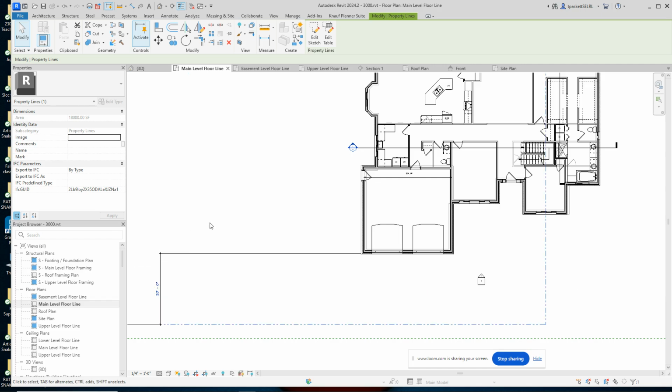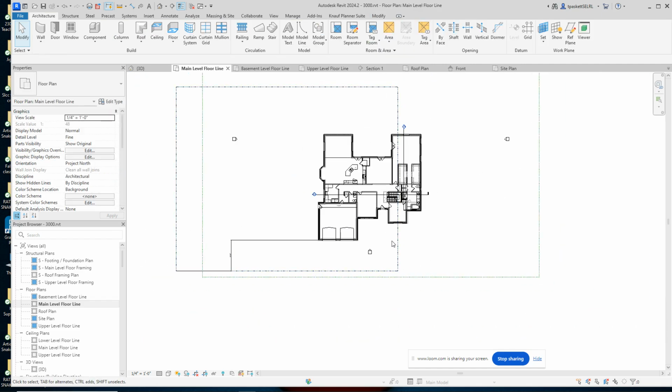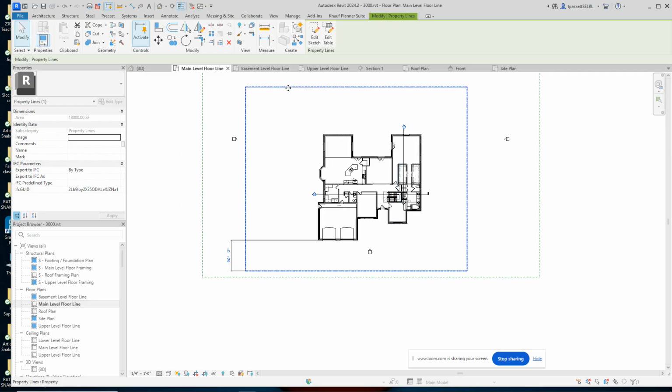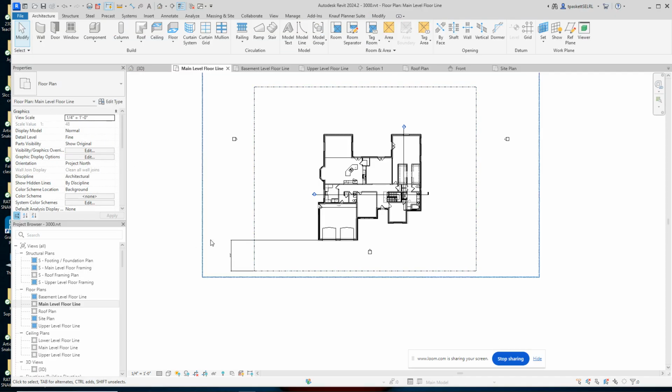Now what that's going to do, that means we've got a pretty substantial front yard and a pretty substantial backyard. Now I'm going to move the whole site plan to the right. You can just use your arrow keys and slide it over. And for this project, just kind of eyeball center your house in the space, because we're not going to go into too much detail here. And then you can delete out that dimension line. You'll put it back in later, but in a different format. All right, so that gives us a property to work with.